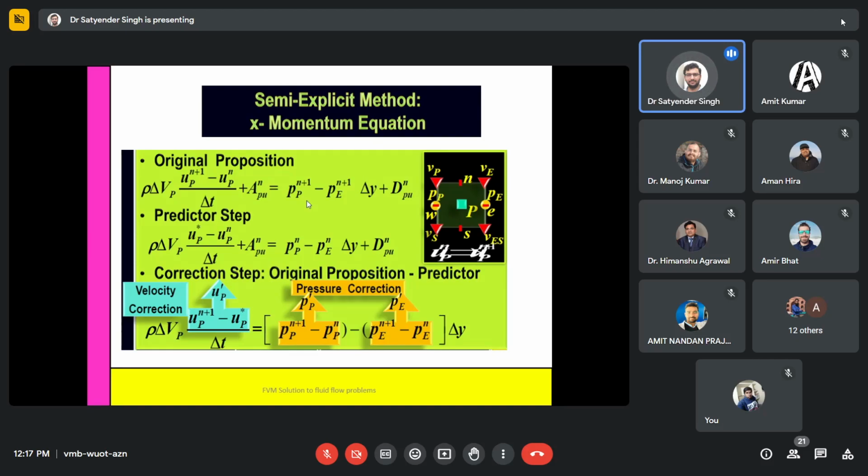At the inlet where you are assigning velocity with some finite value, let's say 1 meter per second, we have to make pressure a function of velocities also, so that by taking reference of some velocity values, pressure can be calculated. Because pressure must be high at the inlet and 0 as it approaches toward the outlet, following some gradient without any equation for the pressure. So that is the illusion actually.